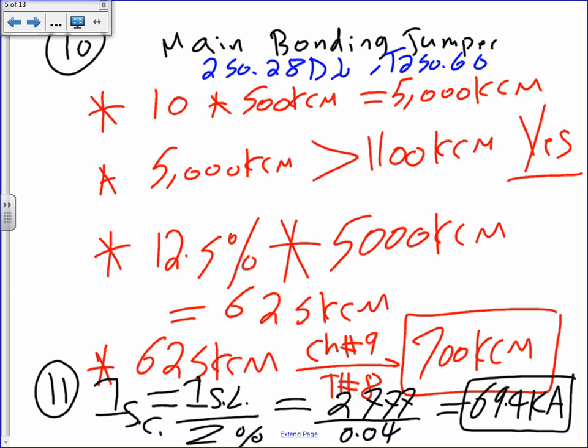If they make a 70, you go to 70. But how would I know? You go to the literature of Cutler-Hammer or Square D, and go to the circuit breaker section. Do you guys remember when Todd was talking about this? You go to the section and find the circuit breaker that gets you the short circuit rating or higher. Okay, that's all. Let's take 5 minutes.